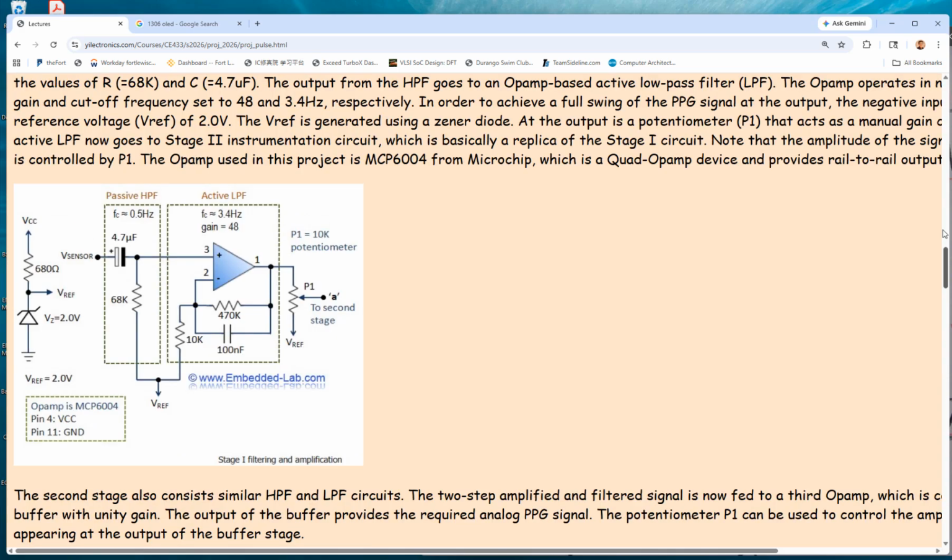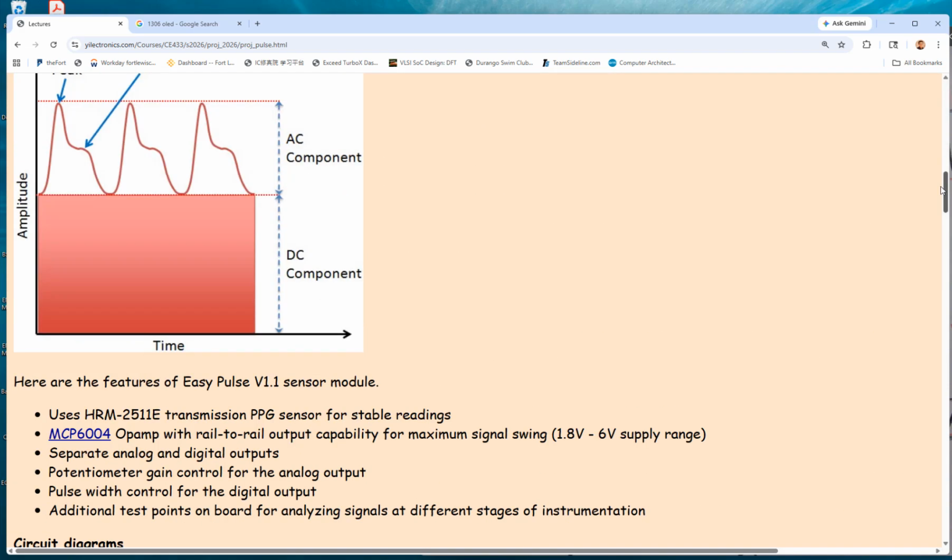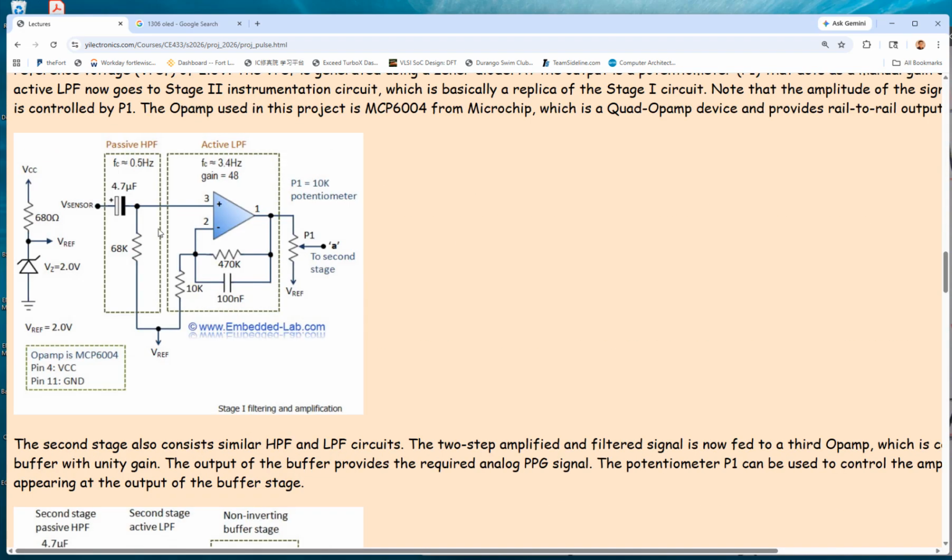If you look at the PCB, with a circuit like this, the PCB already has the traces printed on the board. So how could you add a VREF to this point without being affected by VCC and this Zener diode? That's my question for you guys. I'm just being creative.